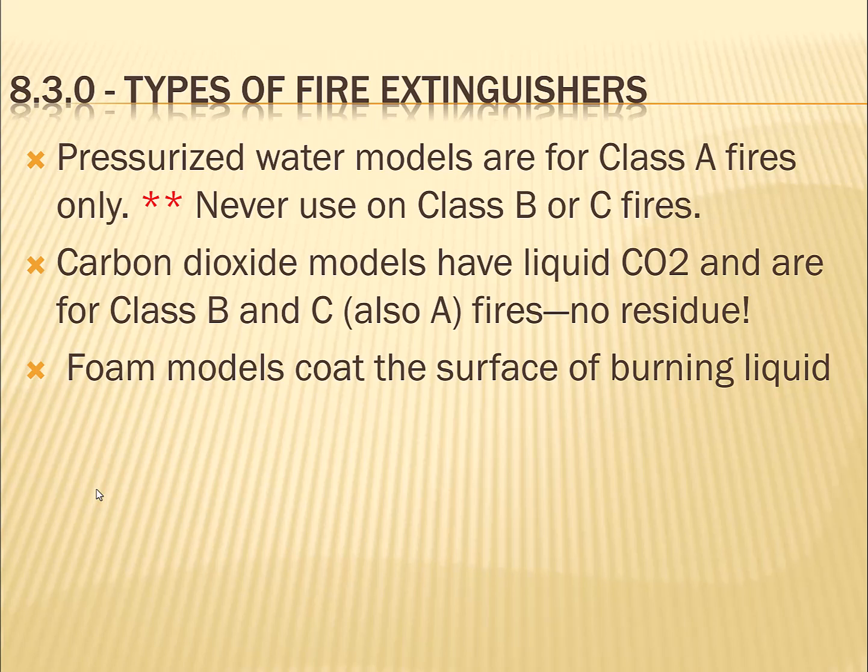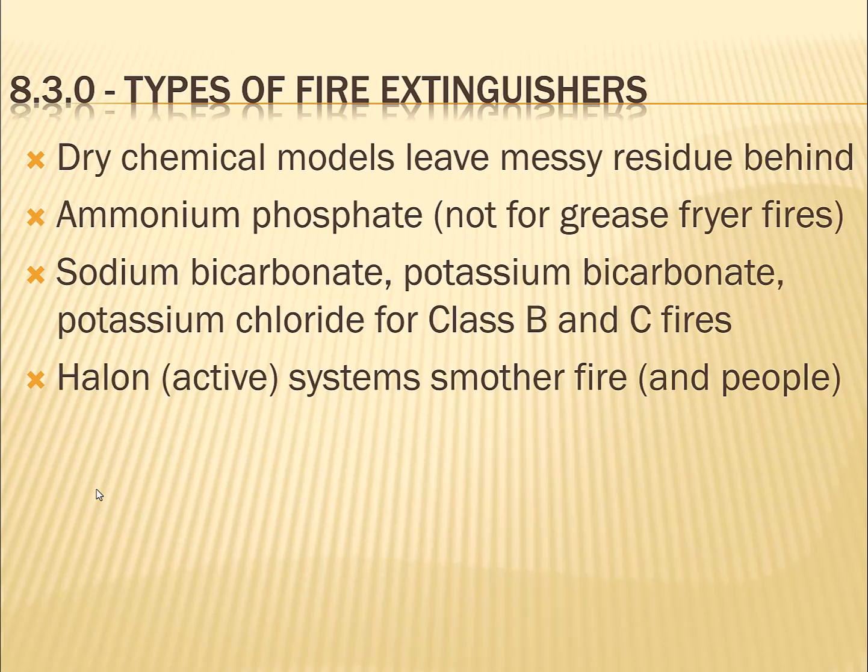So as you can put out a flammable liquid fire, CO2 is the best. Foam models coat the surface of the burning liquid, but again they conduct. So that's the problem with them. Dry chemical models leave messy white powder, looks like a cocaine party. Ammonium phosphate is also dry chemical.